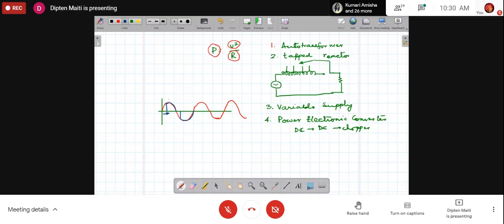However, you see the problem here. You can take a hint from the last class or last chapter. If we do so, although the voltage applied across the system is pure AC, with a sinusoidal waveform, the current drawn by the system is not pure AC. There would be harmonics generated, so that may pollute the system. So we need some method such that the harmonics are reduced, or are taken care of locally, so that they do not pollute the power system.